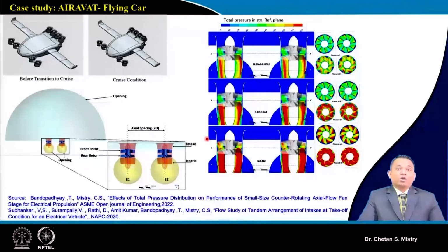The benefit of contra-rotating we have explored with different requirements: higher rotational speed of rotor 1, higher rotational speed of rotor 2, and both the rotors rotating at the design configuration. Basically that helps us in order to manage the thrust. So that's what we have done here.